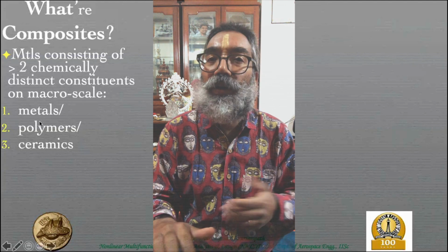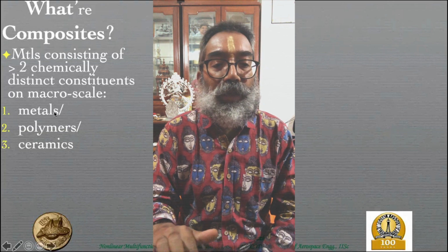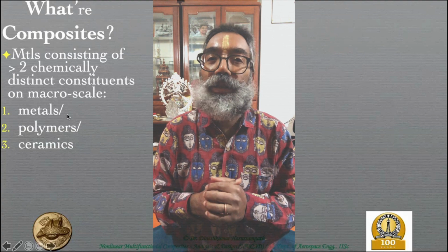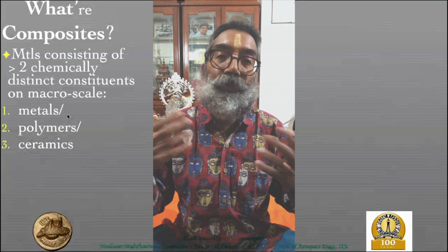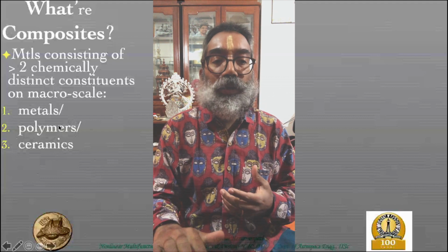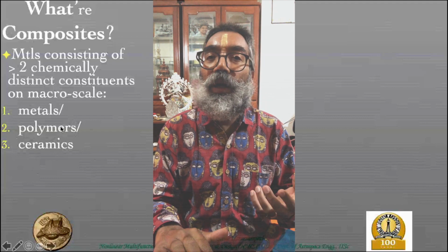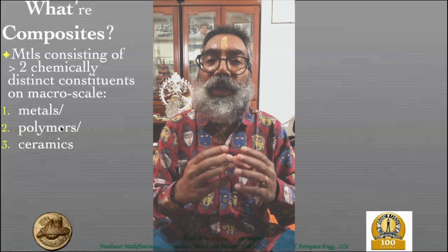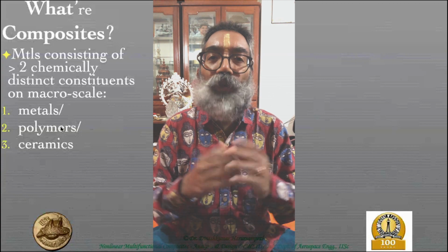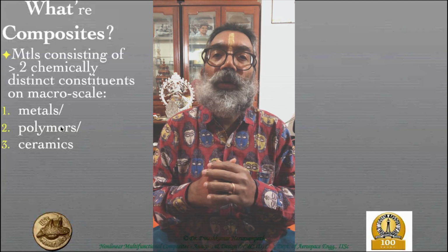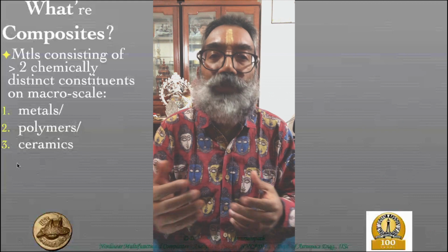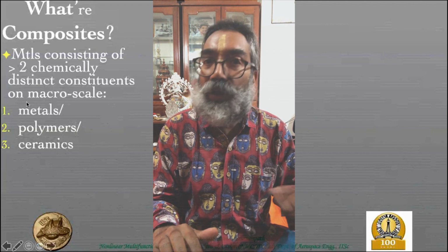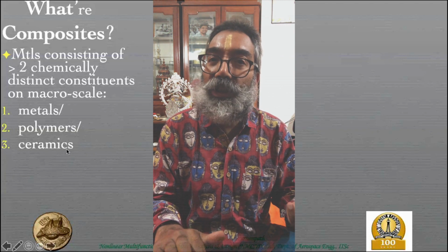So many different possibilities are there, but the idea is that each one of these categories as structural materials has certain advantages. Metals, for example, have ductility, which is not there in the case of most polymers. Even thermoplastics, which offer a slight amount of ductility when you heat, can be in a slightly liquid form but highly viscous, and therefore formability is not as good as with metals. Then ceramics, of course, are highly brittle. So there are certain advantages associated with each.